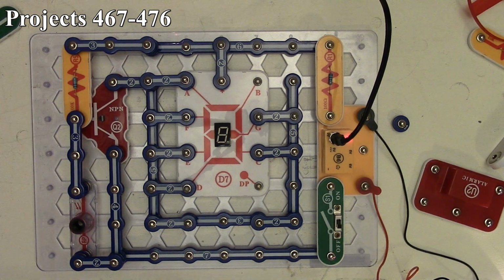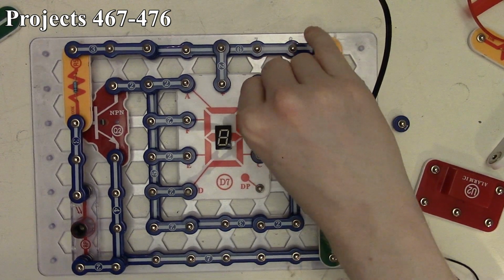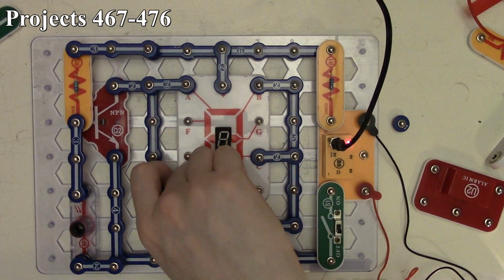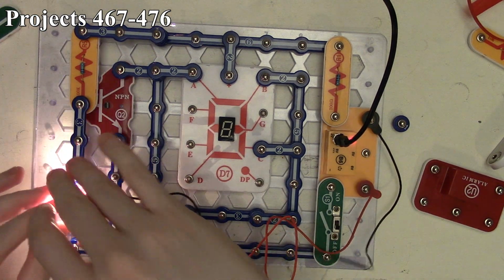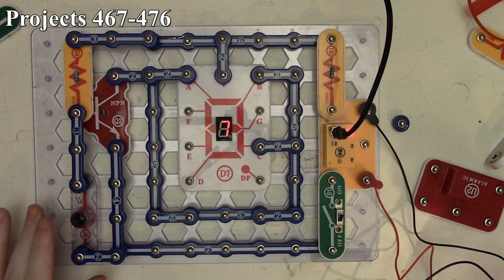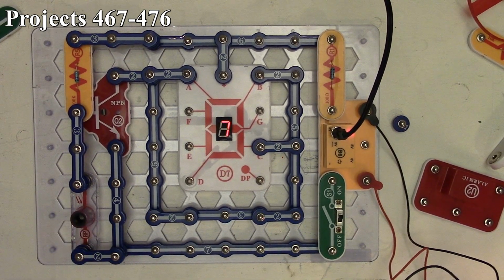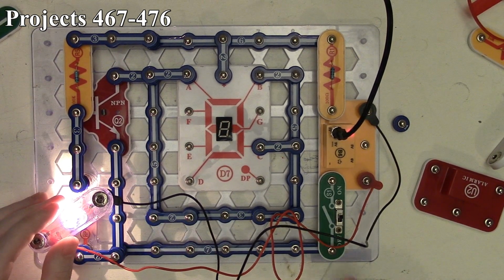So that is 472. So 473, we're now going to display number 7. So we connect points A, B, and C. Take all these away. Take the lamp over. Kind of stick it. Nothing happens. Take our light away. Number 7 begins lighting. Cover up our photoresistor, it gets nice and bright, let the light back in, it gets a little dimmer, bring plenty of light in, and it goes completely out.